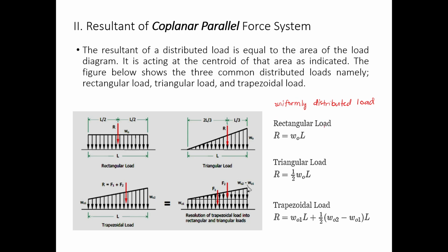I think the only thing that matters here is the location of the resultant force. If it's a rectangular load, since it's a box or a rectangle, the location of your resultant vertical force will be at the center, at the centroid or the center of gravity. If it's a triangular load, it will be at the 1/3 location of the triangle, the center of gravity of the triangle, that will be 1/3 from the base, or from the length of the base of the triangular load.